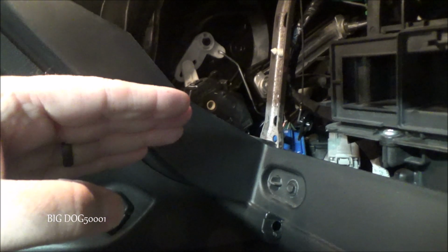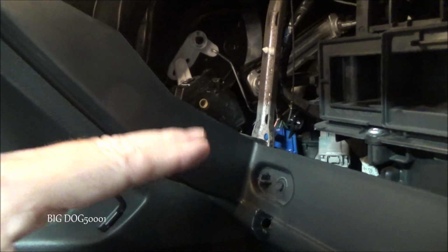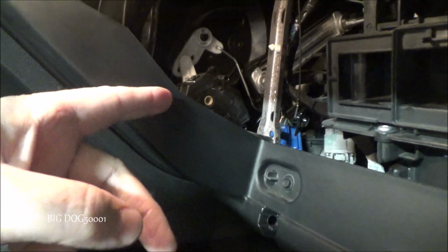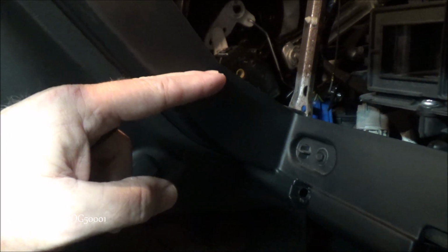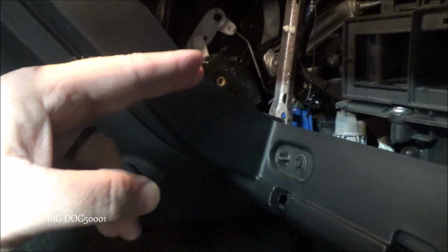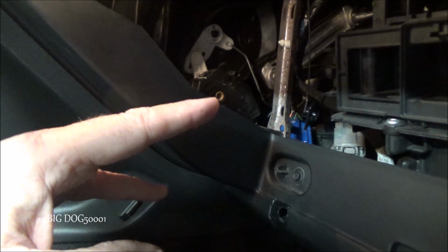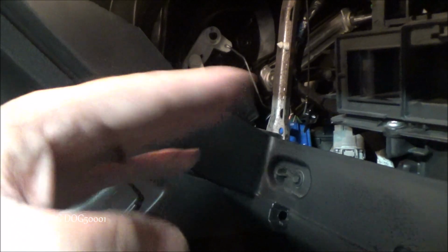But what I was trying to do is see if we could set a trouble code, because I scanned the system and there were no codes. So even though this system is capable of generating codes, it didn't for this issue. So once I unplugged it and tried to move it, then I rechecked it for codes, and of course it set a trouble code saying that the position was wrong. So that's a kind of quick and dirty way to verify your wiring integrity. It's not foolproof, but it's an easy way to give direction.